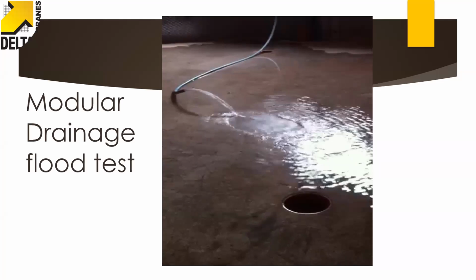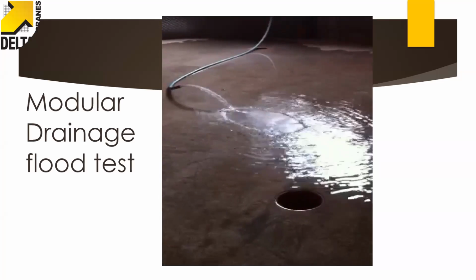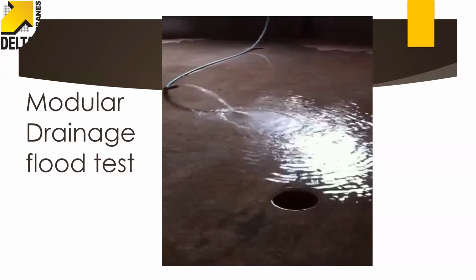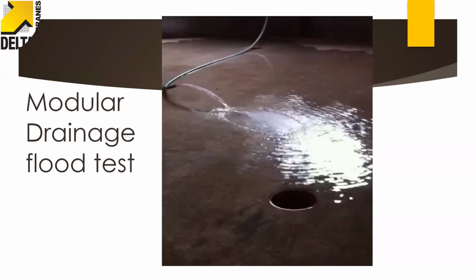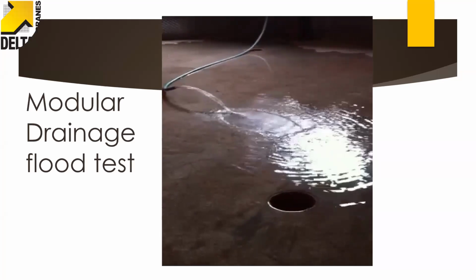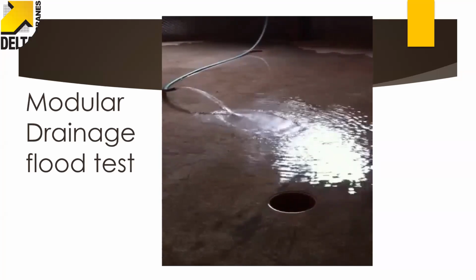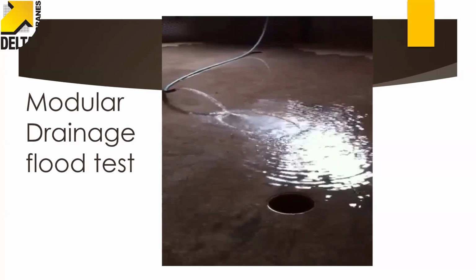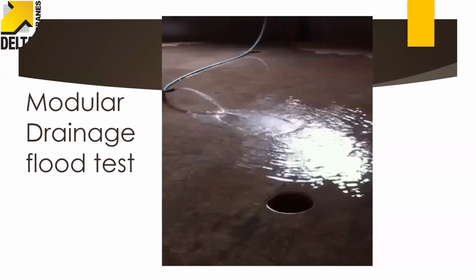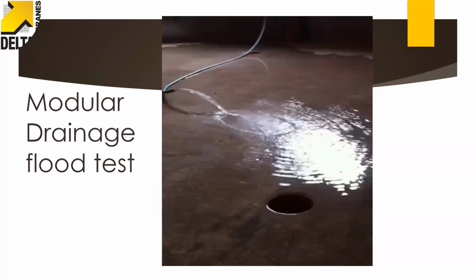And this is a flood test on a modular system. This is one of the drainage upturns after the slab's been formed. We're flood testing it. Why? So that we can identify any low areas that might pond to more than a centimetre, potentially floating a cavity drainage membrane if it's too deep. And we can test the drainage system so we know it's going to work before we close it in. And that aligns nicely with the BS 8102, which says that you should take into account the scope for testing during construction. A really important video there.